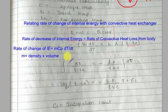Now I will integrate both sides. This term is constant, so it is automatically out of the integration. The integration of dT divided by T minus Ta, that is the integration of 1 by T, is nothing but log T. So log of T minus Ta, and the constant stays out, and the integration of d tau is nothing but tau, plus C1, the integration constant.